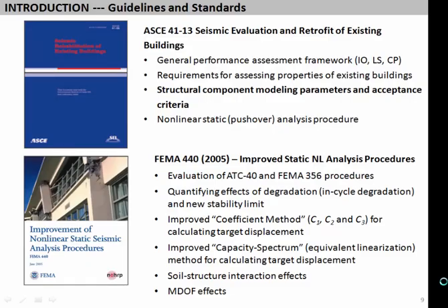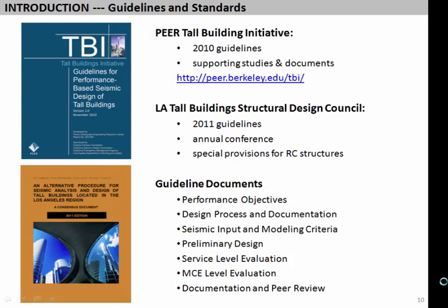I think we should keep in mind that ASCE 41 really was developed thinking about rehabilitation of existing buildings. Also, pushover analysis is really focused towards that. And while there's been improvements in pushover analysis through the years, some of the modeling criteria have not advanced dramatically, in my view, in ASCE 41. And I think that's where we're starting to use nonlinear dynamic analysis in tall buildings, where we're trying to push it, and documents like ATC 72 provide additional information there. So it's really these tall building documents that might be embraced, going from static pushover to nonlinear dynamic analysis.